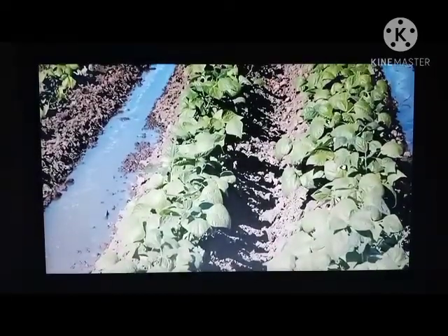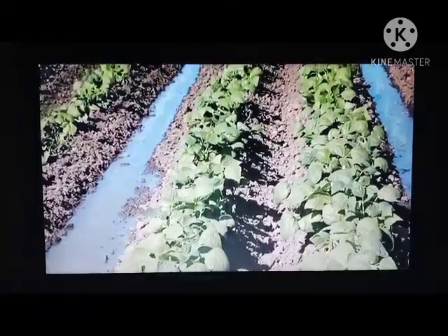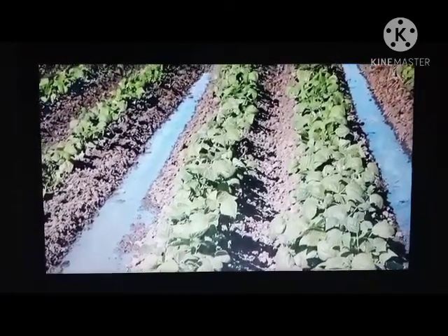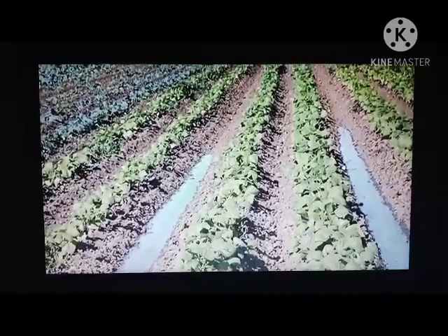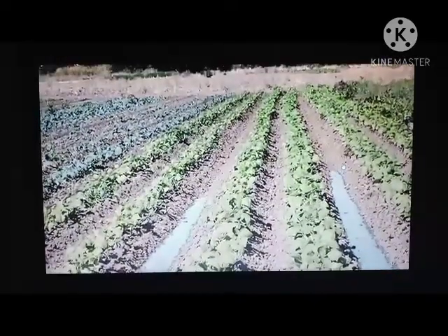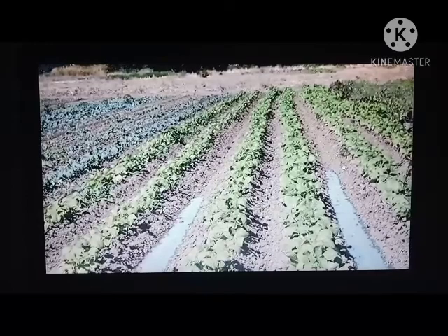One of the reasons we're not putting water down the middle furrow is that the middle furrow is softer than the outside furrows. The outside furrows are where we have driven the tractor, so they've been compacted. That means the water doesn't penetrate straight down into the furrow; it's forced to go off to the sides. When you run water down the center furrow, it penetrates right into the furrow, and it can take a very long time to get to the end of the bed.